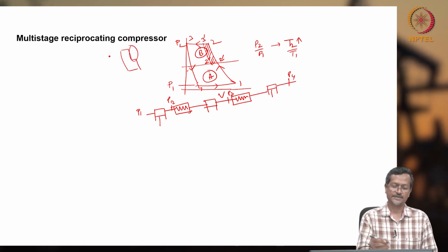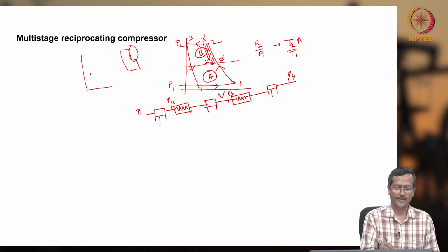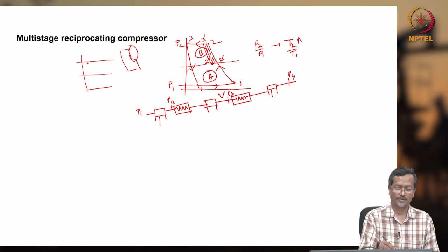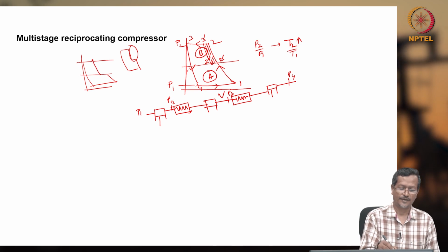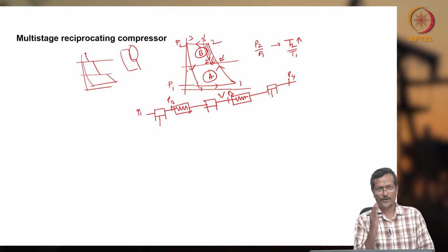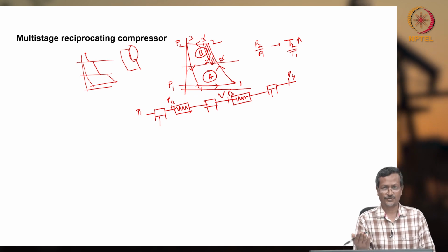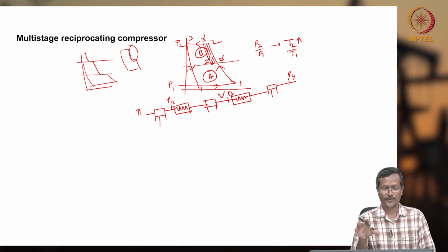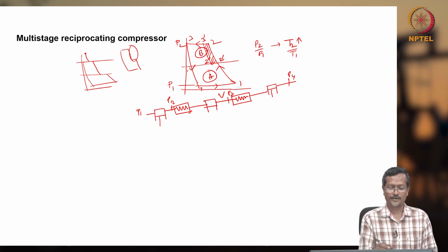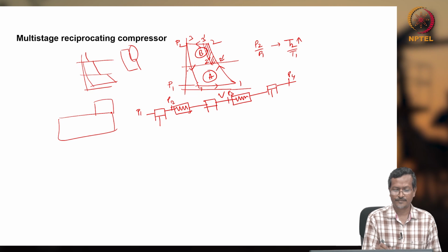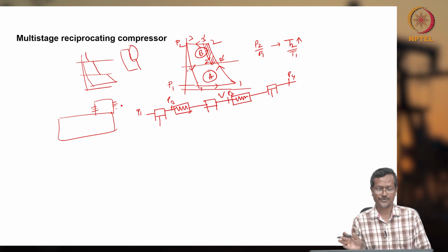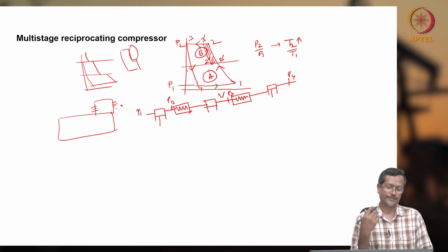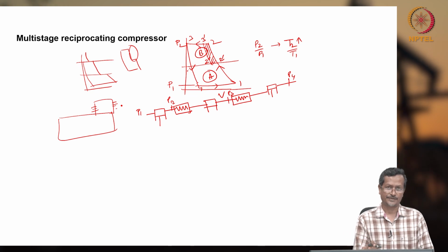If I want to create multiple stages, the same philosophy applies: first stage, cool down, again cool down, again cool down. This way you save energy at every stage. This is the beauty of multi-staging. If you go to any cycle shop with a compression system, you can see a cylinder and some machine elements, and normally fins there. The fins reduce temperature, and if they reduce temperature, the whole system performance increases.